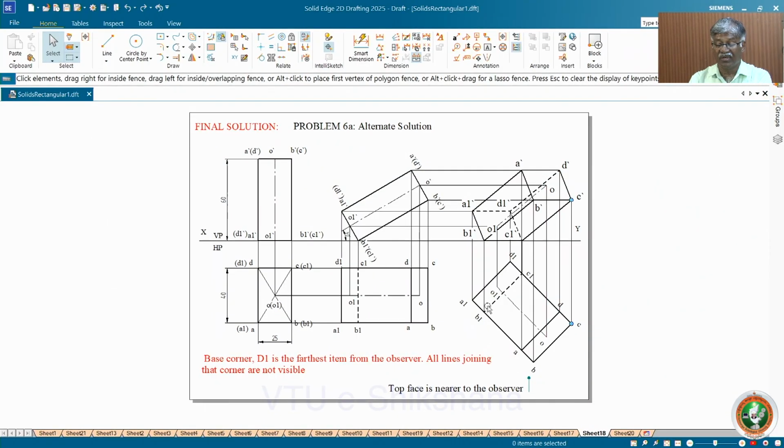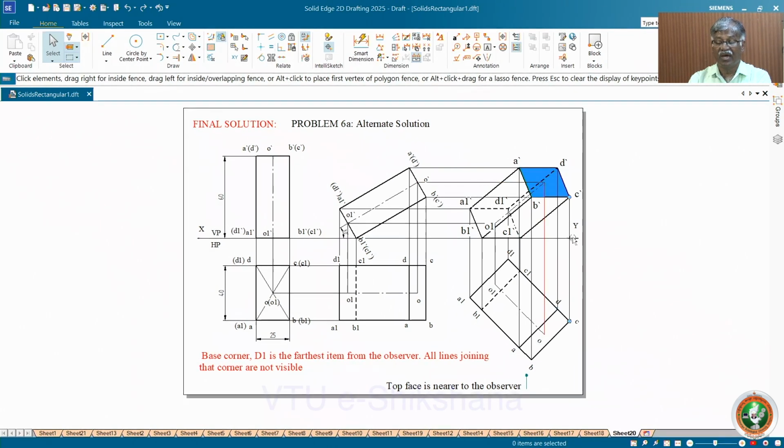The top face is nearer to you, so definitely this particular face is visible. With shading I have used this. You can see this and try to imagine and work out the problem. It's better to have imagination, but if you use the key surface method, no imagination is required. The only criteria are visible surface, invisible surface, then boundary lines, then for the invisible surface it is just dotted, other than boundary lines, then crossing line fence. So this is how you can complete.